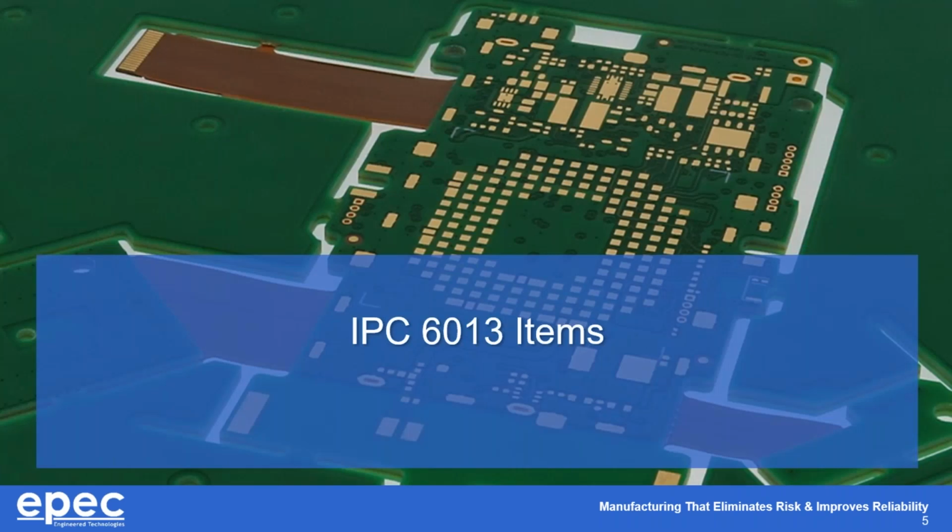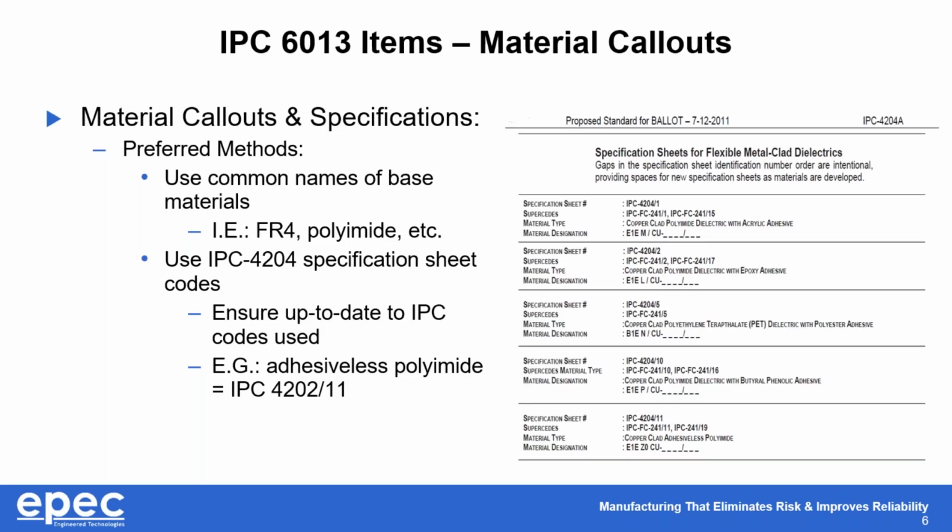Now, starting off, we're going to start with the IPC 6013 items. And as I said, we're starting out with the callouts and specifications. Our preferred method of doing callouts and specifications involves using the base common names of materials, such as FR4, polyimide, flexible polyimide, Coverlay, generic broad terms.